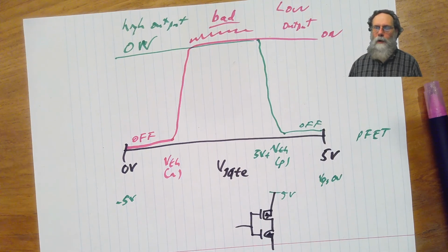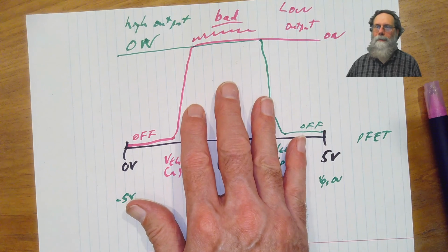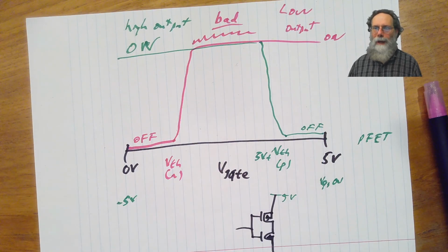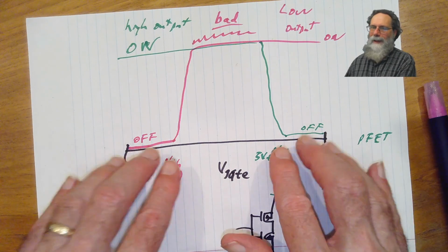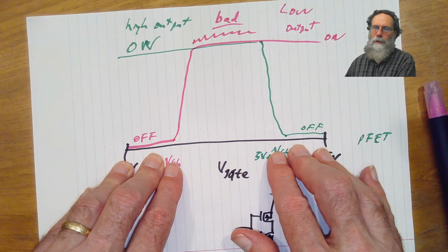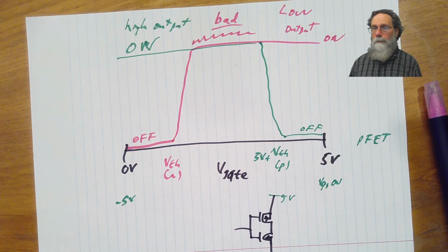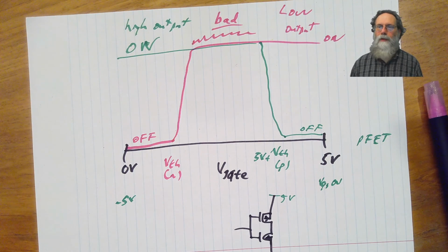So you'll get a spike of current, but it'll be a very short duration and so won't contain a lot of energy. There'll be a power spike, but the total energy in that spike will be kept small, and so you can still keep things fairly efficient. I mean, you do lose some energy during that shoot-through current time, and there's not a lot you can do about that if you have to run a high voltage and you've got your transistors with fixed thresholds. So basically the solution usually is run fast, make that gate change very rapidly. And we'll look at that in a subsequent video, how to make a rapid transition on the gate.